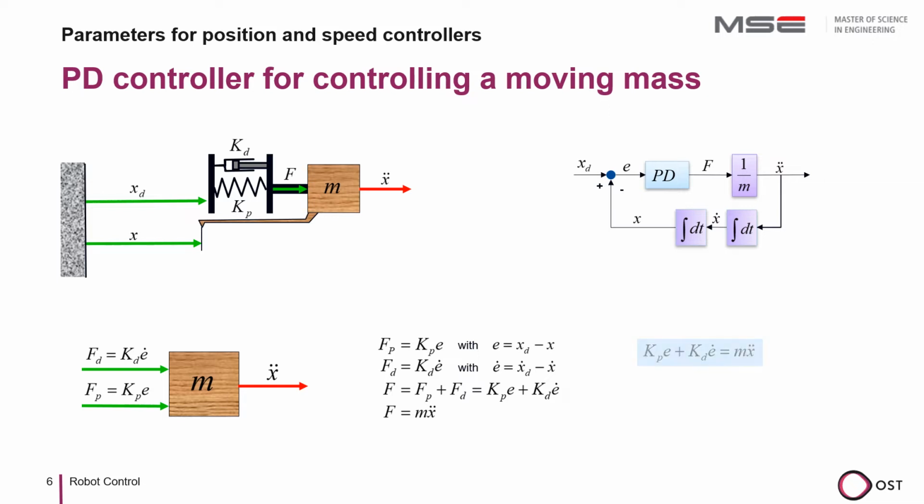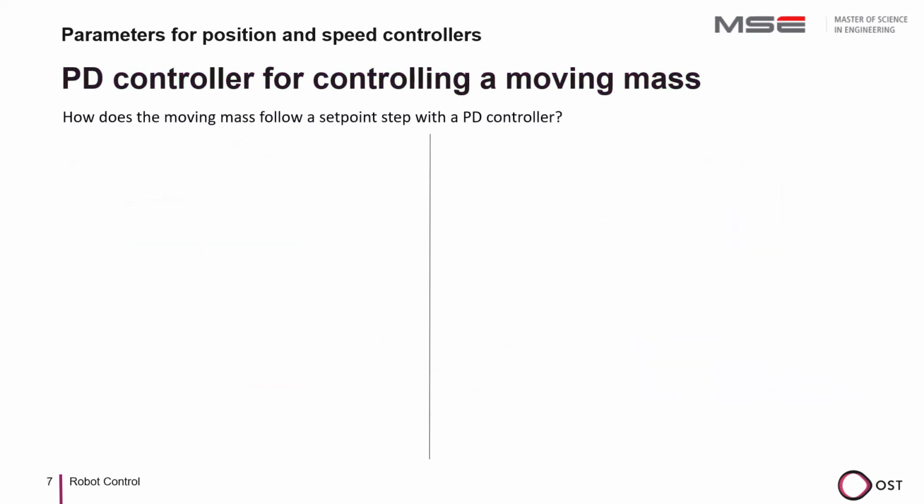Newton's equation can be combined with the equation of forces to form a differential equation. To be able to solve the differential equation, we write it out so that the state variable x becomes visible. If you know the theory of the vibration equation, you can continue directly with the derived equations. For the others, I will briefly show the homogeneous solution of the differential equation.